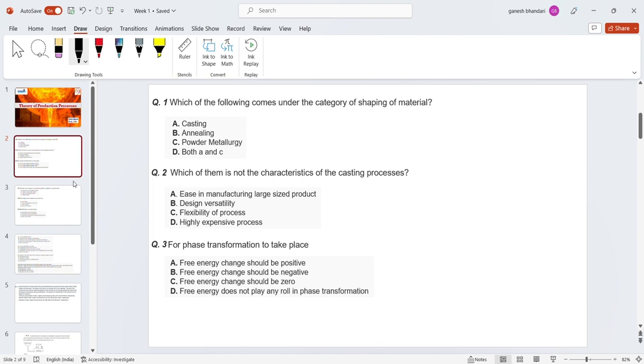Yeah, right. Suppose you are going to check the feasibility for a particular reaction, say tin itself: SnO2 making tin plus oxygen, and then if you are using a reductant, C plus O2 making CO2, or CO plus O making CO2. Then you will make a delta G versus T plot, or check the slopes of both equations and at what temperature they cut. If they are not cutting each other, then no reduction is possible from that particular reductant. Then you will go for another reductant or something else.